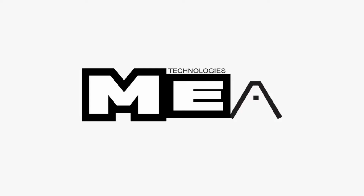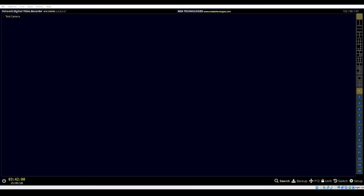Today we're going to be going through the network setup portion on your Emstone NVR. So I'm going to load up our NVR, which I've got set up here. And you see in the top right hand corner, I've already got an IP address. These are set up from the start to connect to a DHCP server and request the first available IP address from your modem or router.